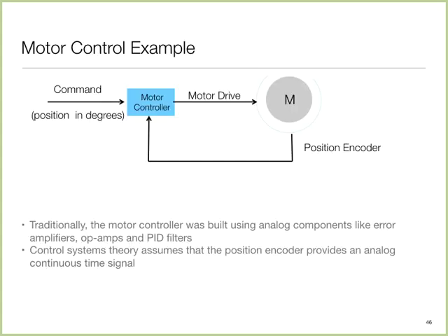Taking that as an example, let's imagine we have a motor controller. The motor is equipped with some sort of position encoder, which is sensing the motor's position, and the set point is basically the command. So we say the motor should be in a particular location, and the motor controller internally takes the delta between the set point and the position encoder, and based upon that computes how much voltage or current or whatever to apply. Traditionally, these kinds of systems are done in a uniformly sampled manner.